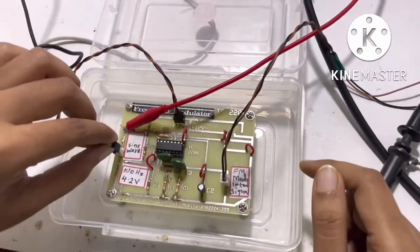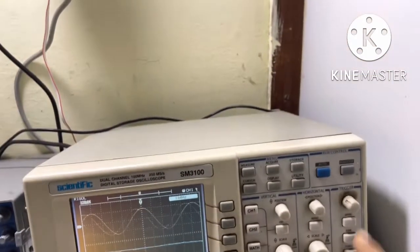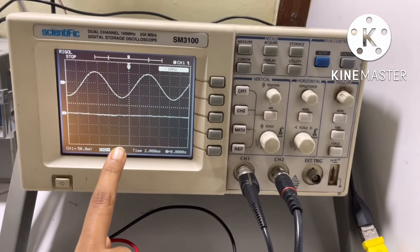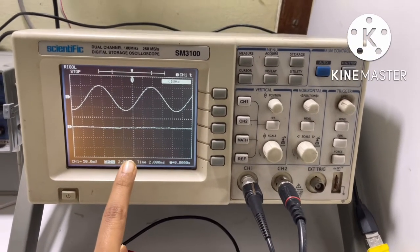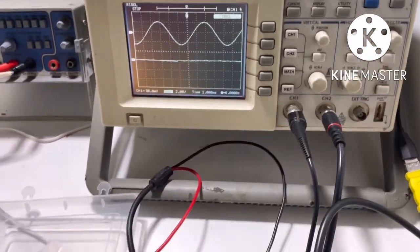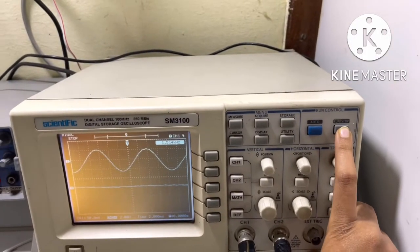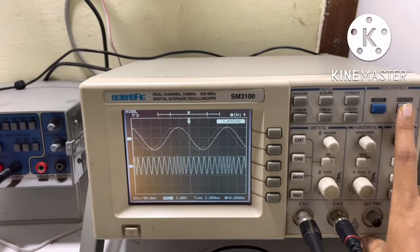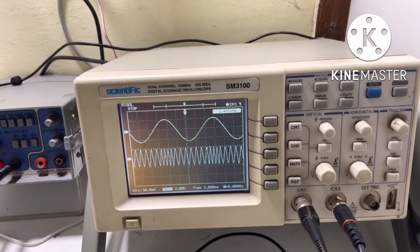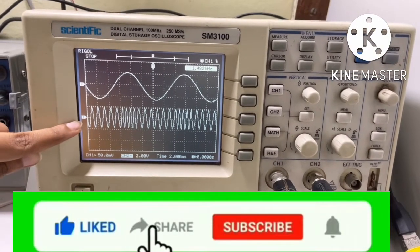Now I am connecting the input and disconnecting the output and keeping it at stop mode. This is the message signal having frequency 100 Hz and peak-to-peak voltage of 4.2 volts. Now I am connecting the output and keeping it at run mode. I am keeping it at stop mode. See, this is our message signal and this is our FM modulated signal.